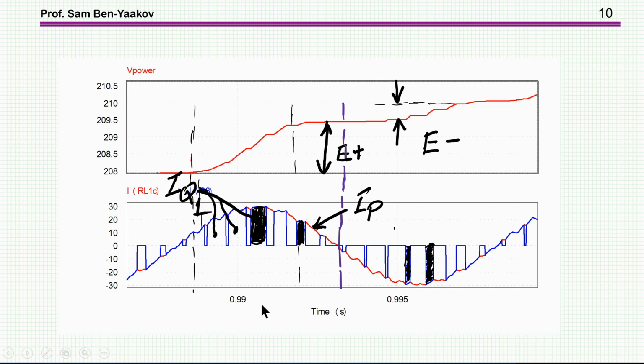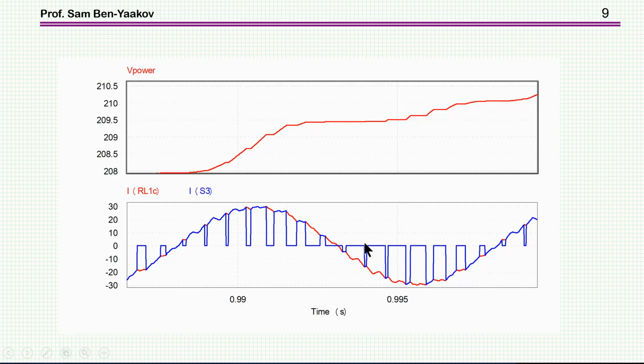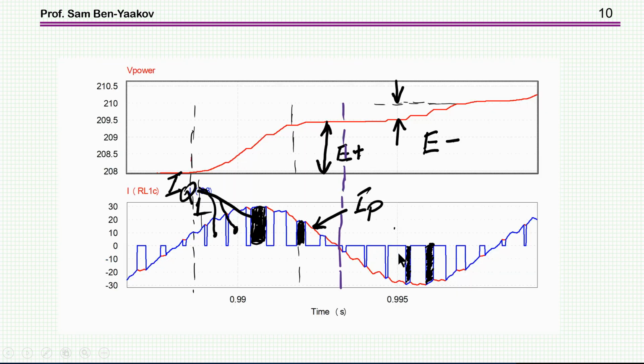Now, obviously, this is for an outgoing current, okay? This is for a current like this. Now, if the current will be ingoing, it'll be reversed. So over a long period of time, the average is the same. So one can say that the dissipation of the transistor at each half cycle is the same. But this is for high frequency. At low frequency, this is incorrect. So these are the issues that need to be taken into account, and you can see it here.